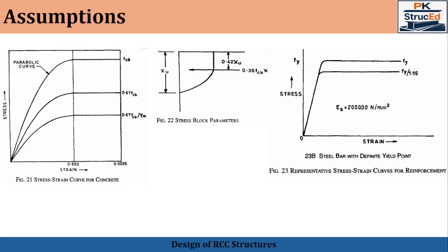So what is the actual behavior of concrete? The concrete exhibits a non-linear stress strain relationship. The stress increases with the strain up to a maximum. Beyond a certain strain, the concrete crushes suddenly, in which the concrete failure is considered brittle without giving any warning. So as per IS 456, the characteristic compressive strength of the concrete is denoted as fck.